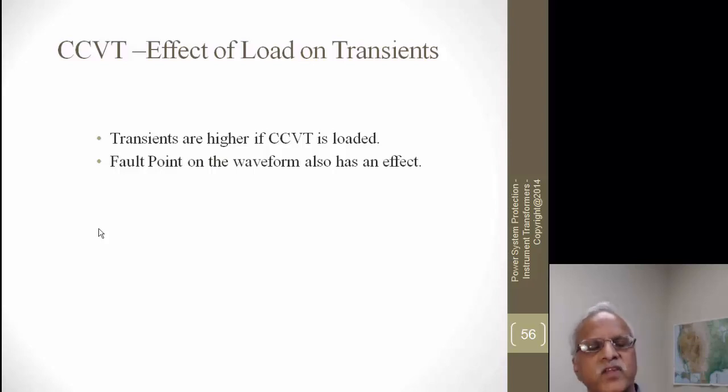And then we went through the standards, how to specify a metering class CT and how to specify a protection class CT. We looked through that, and we also looked at the C rating, which is typically used for protection class in the United States, and then there are similar ones such as TPX, TPY, TPS, and also 5P20, which we covered, for IEC specifications also.